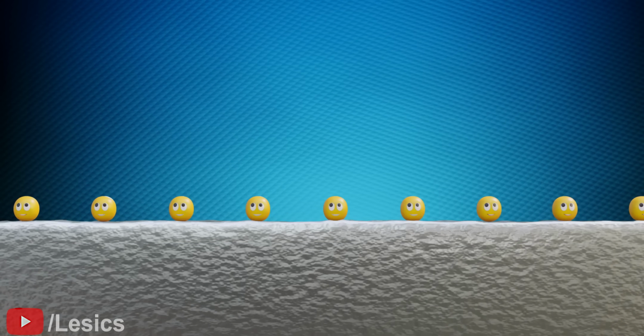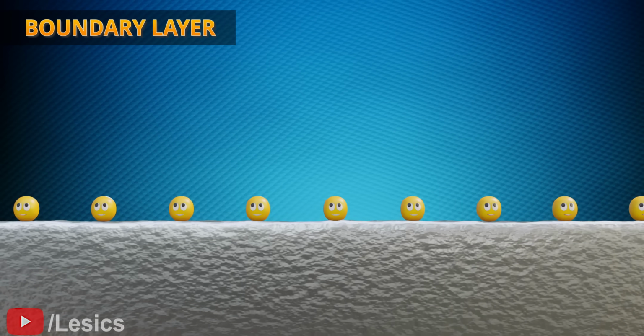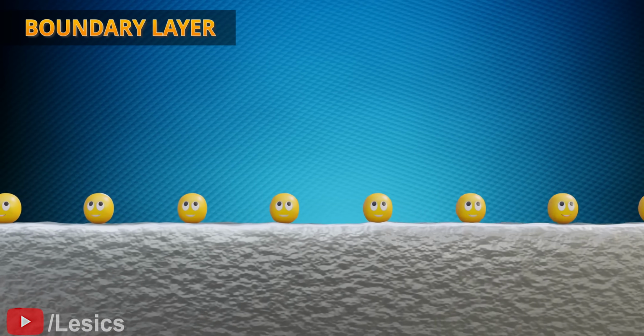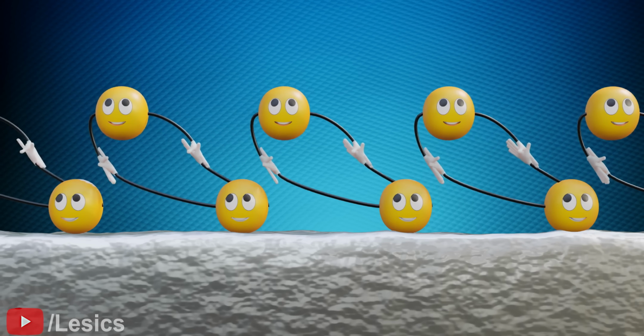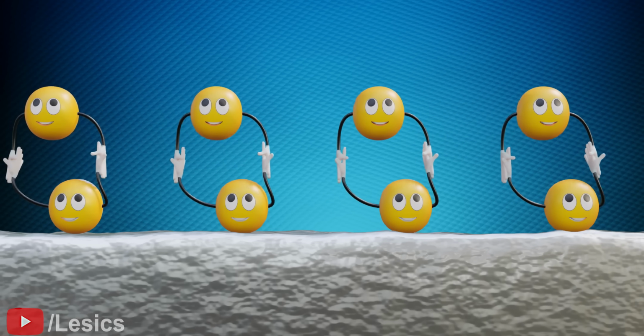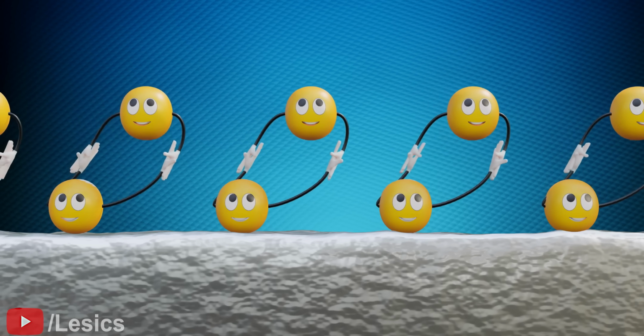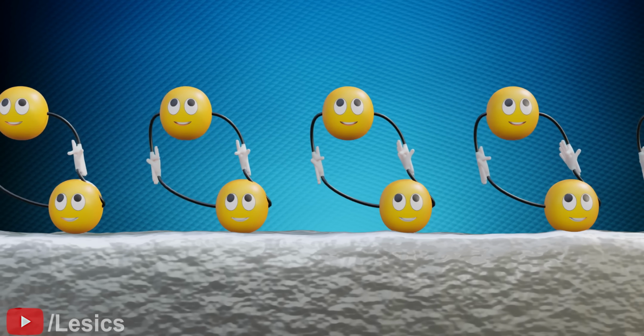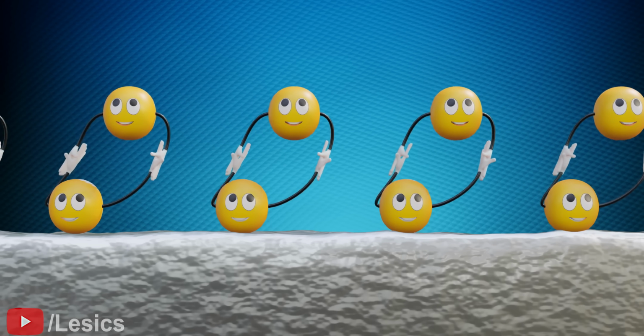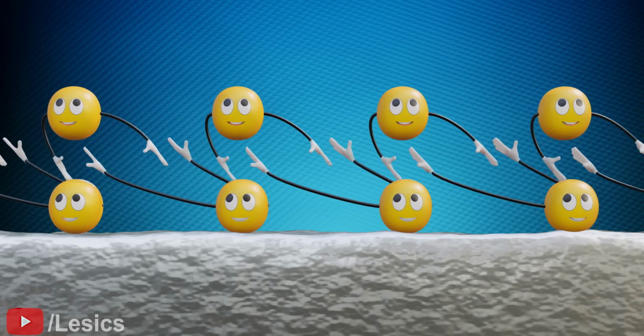To improve this design further, we need to understand a key concept called boundary layer thickness. We can observe in this system that the fluid particles which are in close contact with the disk adhere to it and form a stationary layer. The next layer of molecules tries to pull the stationary layer in the flow direction. However, in this process, they lose some energy to the stationary layer molecules. The same thing happens with subsequent layers.